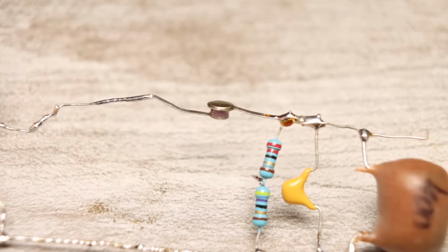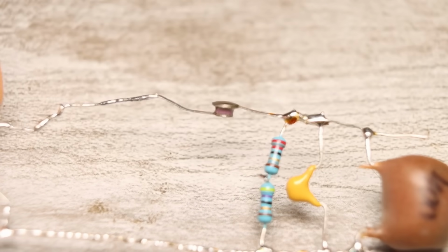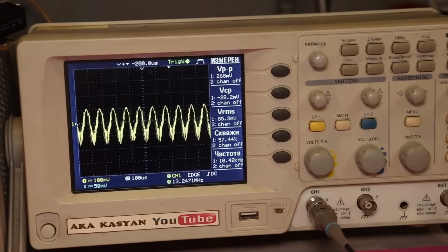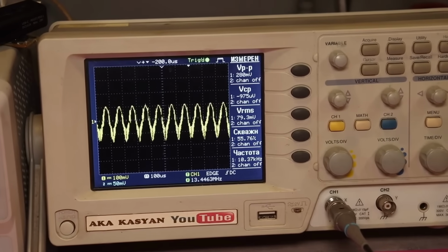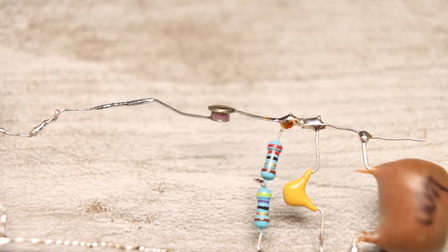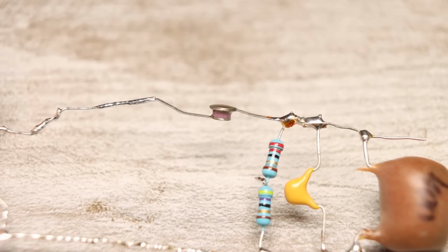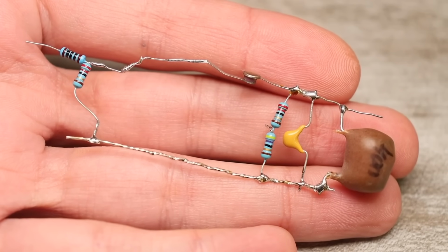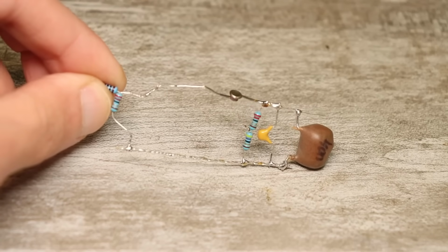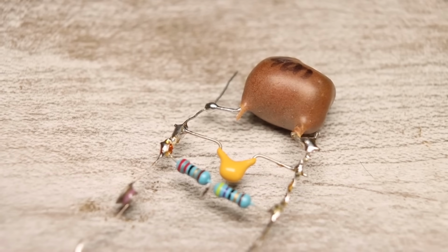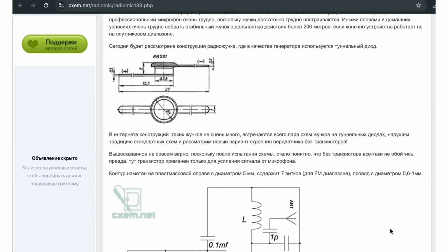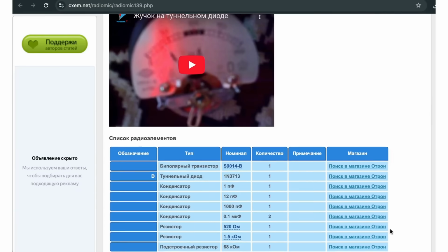It's important to understand that, initially, there are micro-oscillations and noise in the system. The process of charging and discharging the capacitor changes the voltage in the system, creating surges and jumps, which leads to changes in the current through the tunnel diode. In other words, you could say the diode and the circuit support each other's operation. With a ready-made oscillator, nothing stops you from building a radio signal transmitter based on it. Back in the day, I used to tinker with transmitters like these, and I even have a few articles left on the soldering iron website.